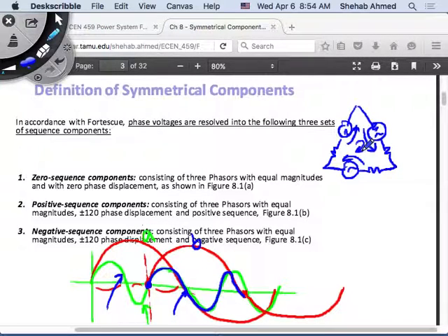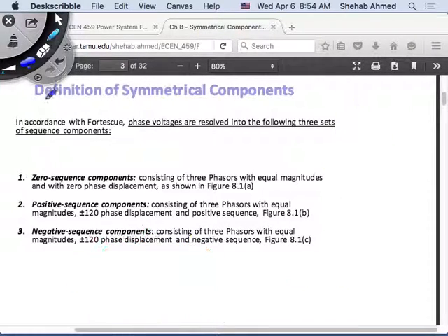Anytime you have a zero sequence component, zero sequence components are components that are equal in magnitude and phase. So DC is equal in magnitude and phase. This third harmonic is equal in magnitude and phase in a three-phase system. Fifth harmonic would be equal in magnitude and phase in a five-phase system, right? So it's different in different numbers of phases, but this is what's called zero sequence. Zero sequence are just components that are equal in magnitude and phase. And what they do here is, in the delta they will add up. What do you think they do in a star?